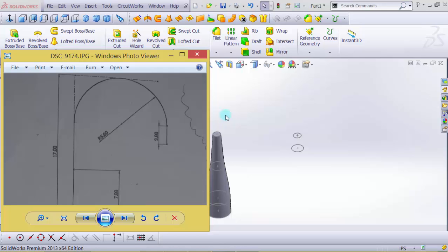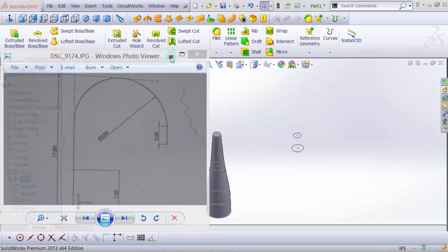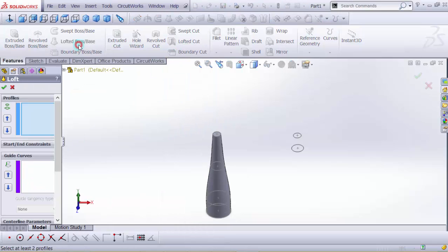So in loft you can not have center lines, you can have guide curves. See, guide curves. So actually, if I could zoom in here, you can see that, look, the guide curve does not pass through the center of the closed loops or shapes, that is these profiles. It passes through one point at the very edge or perimeter of the shape.